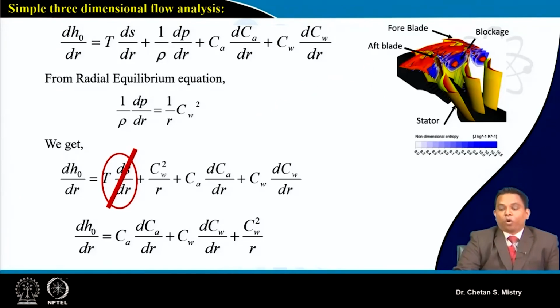The blockage of our flow has been represented in terms of entropy. When doing post processing, in order to discuss the losses, people conventionally use the measurement of entropy change. The measurement of entropy is always a challenge, but we convert it in the form of pressure and temperature.